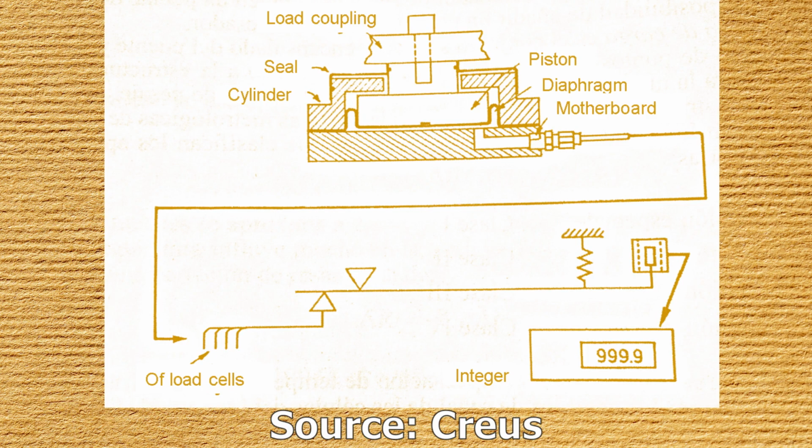Hydraulic load cells consist of a piston on which the load rests, which exerts pressure on a hydraulic fluid. Depending on the load and according to the known piston area, a pressure is created in the oil, and it can be read on a Bourdon gauge, and therefore indirectly reflects the load. Adding the hydraulic pressures of various load cells and applying them to an electronic or digital transmitter yields a signal that can be read off an indicator and used in electronic weighing systems.